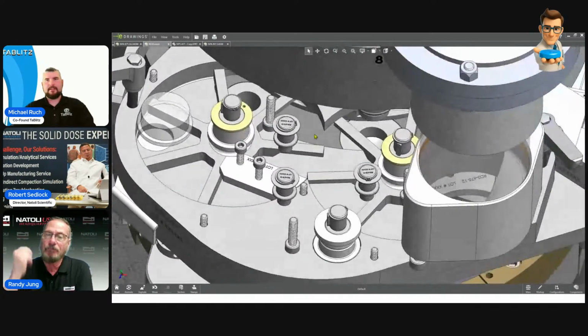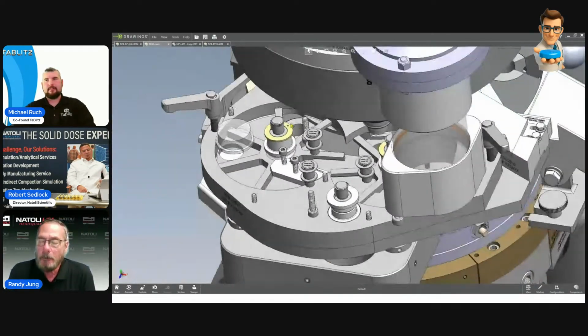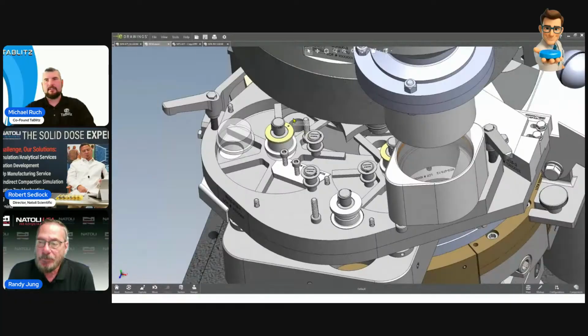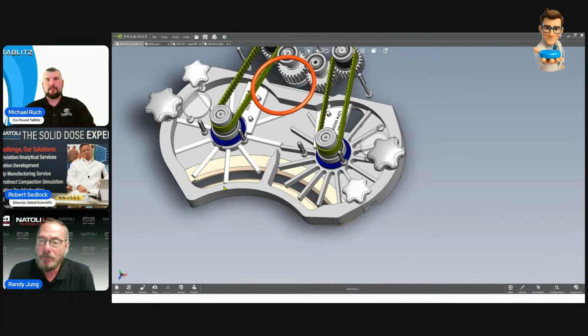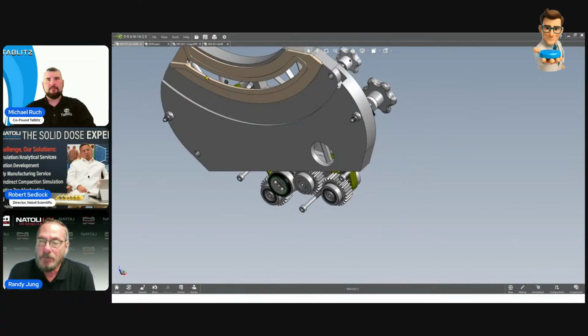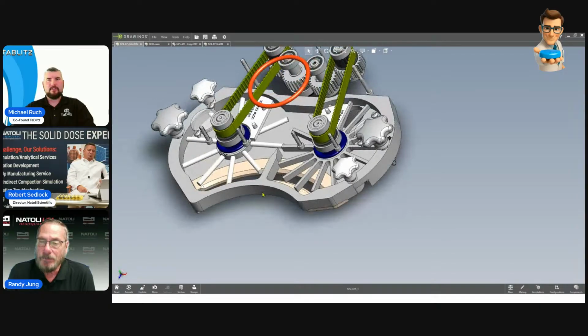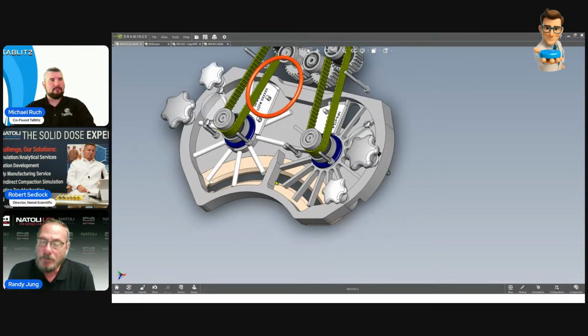It's actually displayed here. So this is the original feeder pan for this design. And here's the die, and here it's pushing that powder into the die. Whereas changing that aperture opening to be a little bit bigger than the die bore opening is what this is intended to do, to prevent how much powder you're moving across the tray.